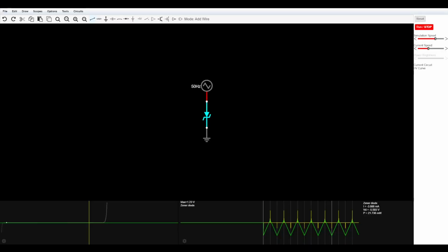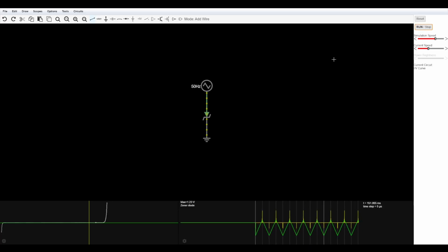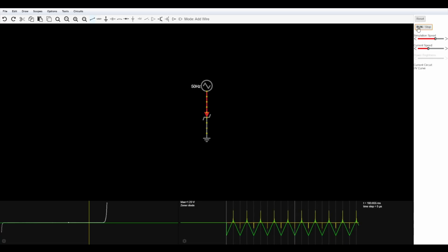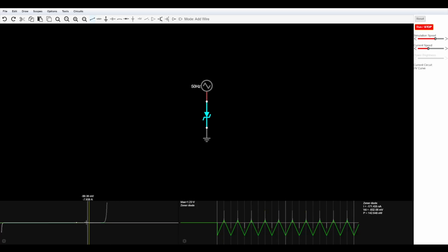All right, and this with Falstad here. This is an IV curve. Now in forward bias, it works basically like a regular diode, but let's just take a look. It's, I don't know, around 1 volt. It starts to go up. Sounds about right. It's going into the thousands of volts, but lack of resistors and all that. And then it hits breakdown really early compared to the regular diodes, but that's the point. Around, I don't know, 5.8 or so.